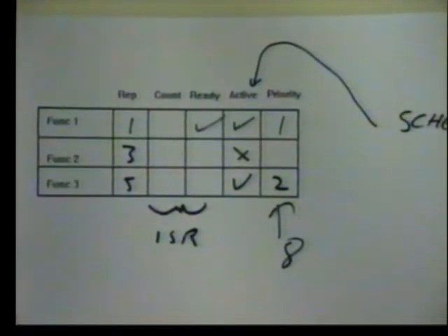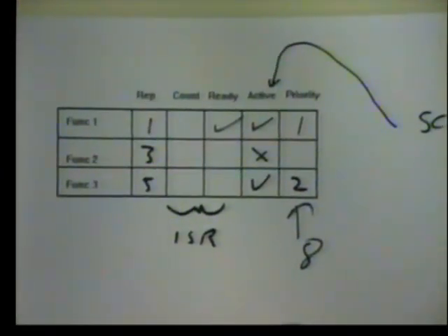So I'll leave you with this final picture. It was a very simple structure. It's a true multitasking operating system. It works only because it obeys the rule that any function that is executed must be completed, and all the functions must have an execution time that is faster than the rate of arrival of the fastest routine. Given those constraints, which are standard for real-time systems, you can implement a multitasking operating system using a very, very simple array structure such as this.